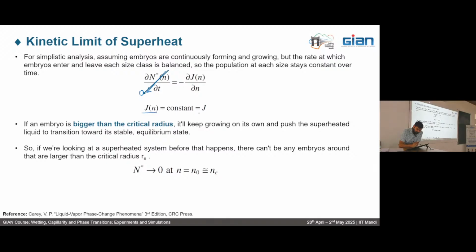So now Jn, which we defined as the excess molecules, remains constant. It means that if we are talking about bubbles having, let us say, a diameter of 1.2 micrometers, then that vapor bubble number would always be the same in the system. Let us suppose in a system we have thousands of molecules, among those 1000 we have 100 molecules of 1.2 micrometer size; that number should remain constant. That is what we are imposing here.